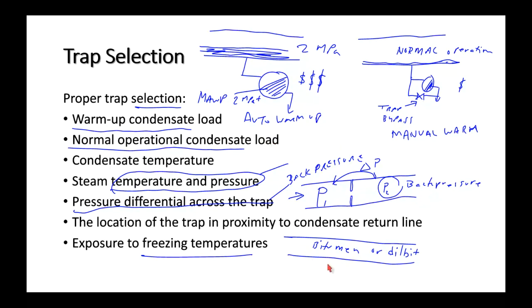Anyway, getting back to this pipe that has got dilbit in it, and this stuff might congeal or solidify at low temperature. So what we'll do is we'll take a tube, maybe like a 1/2 inch stainless steel tube, and we'll put it underneath the insulation, and we're going to run steam through it, and that's called steam tracing.